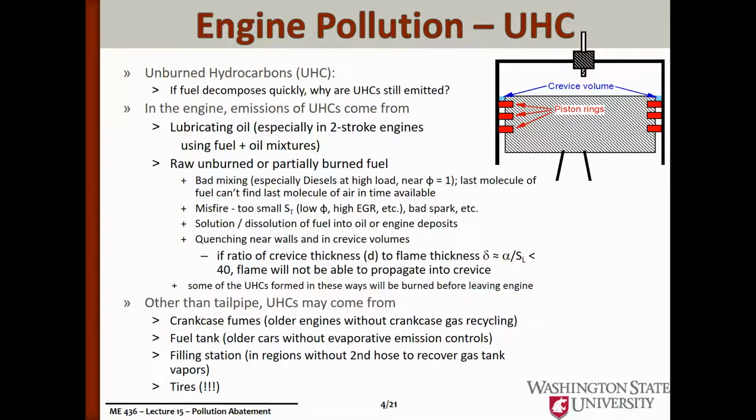The unburned hydrocarbons are slightly different than the carbon monoxide. The majority of the unburned hydrocarbons come from the areas in the corners of the engine along the wall where the flame gets quenched. They're more products of incomplete combustion than of the equilibrium type reactions the way carbon monoxide is.